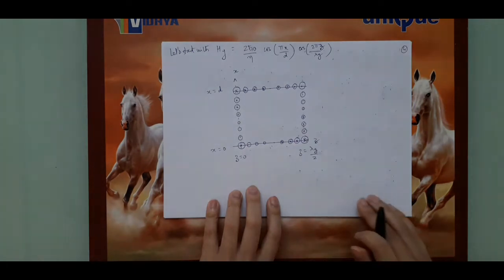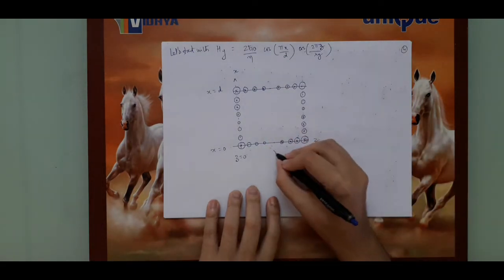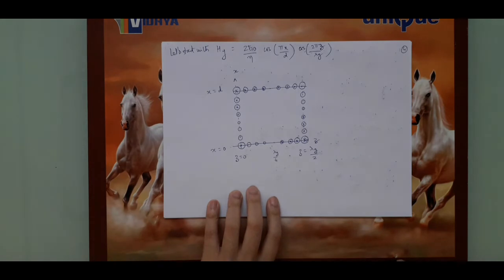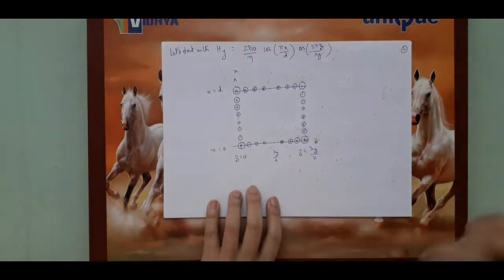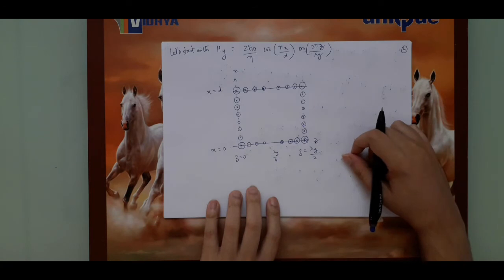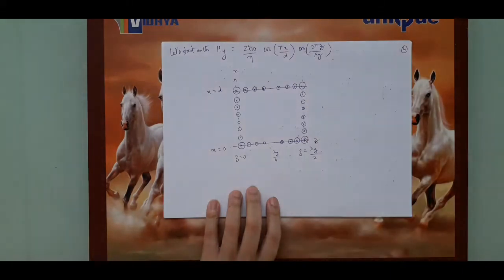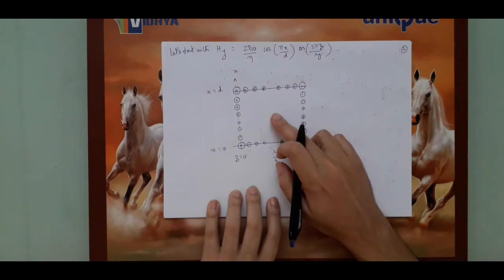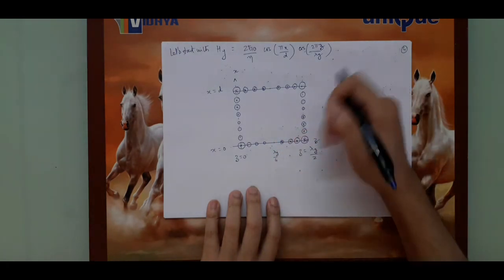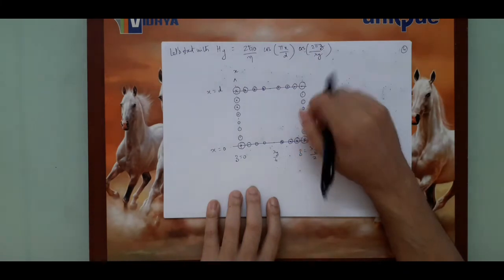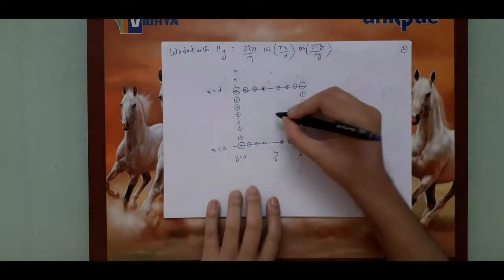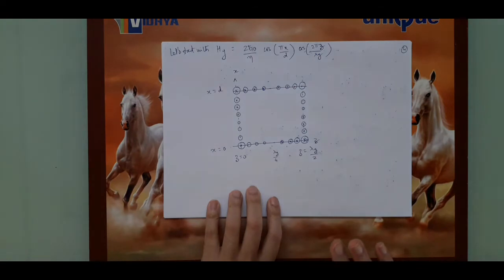over here. Let us say when x is d by 2 and z is lambda g by 4. What will happen at this point? At this point, when x is d by 2, the field will be 0. And here, because of this lambda g by 2, even this cos term would become a cos of pi by 2. So therefore, you will have a minima over here also somewhere.